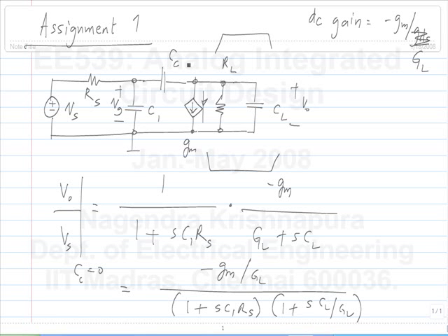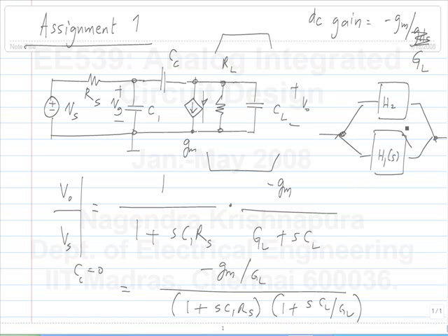So typically you end up getting a 0 when you have a transfer function like this. Let's say you have two paths that combine. Okay. You can expect something to happen to the numerator. Again, it doesn't necessarily always give you a 0. You can make it so that it doesn't give you a 0, but you can expect there to be some 0 when you have multiple paths combining to give you the output. Okay.